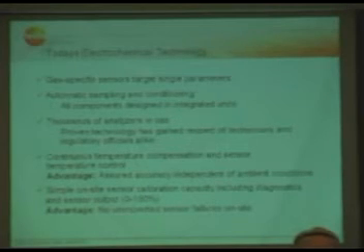And this makes sure that it doesn't matter at which day or in which location you are measuring, the gas conditions are always the same at norm conditions. That means the dew point is almost 4 degrees C, stable, and therefore you can compare the readings.